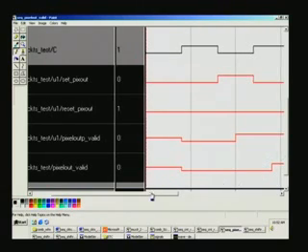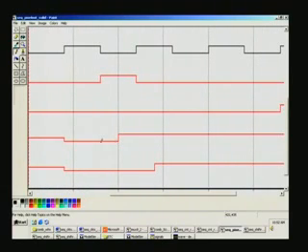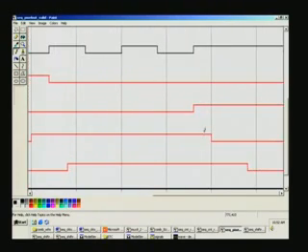And coming to this here, the last two are pixel out, and so you see here pixel out P is here, and this is staggered by 1 clock pulse, and when it goes low, this also follows suit. So it is nothing more than this. This is the basic logic in pipelining registers also, which we will see in more depth when we go to adders and other multipliers, arithmetic expressions, how to evaluate them, compute them, how to evolve new algorithms for that also will be seen in that.